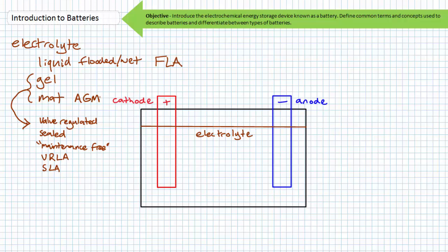The valve's only function is to vent the battery in the event of internal pressure exceeding a safe value, and a gas's loss to venting cannot be easily replaced. For this reason, the electrolyte in VRLA batteries is often over-provisioned. The reduced maintenance requirements and the ability to use or store a VRLA in any position comes at a price of reduced mobility of the electrolyte, and in contrast to a flooded cell, the chemical reactions ordinarily proceed at an impeded rate.